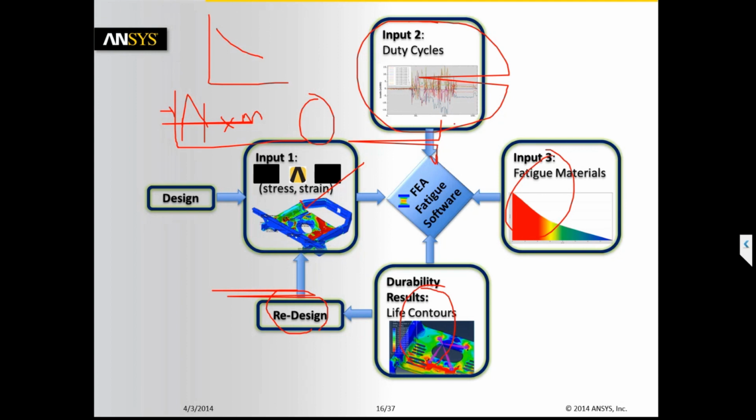When you are running a fatigue analysis independently versus along with the ANSYS Workbench, whether it is ANSYS fatigue or ANSYS nCode fatigue, the advantage is it helps you redesign quickly, because your geometry can be quickly optimized, or you can use the optimization package within ANSYS nCode, where you can change the geometry, take it to the fatigue and update the results. You will be able to see the influence of your change in geometry on the fatigue life.